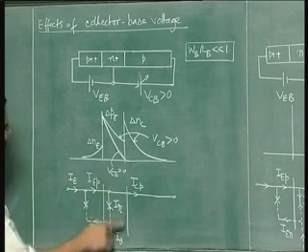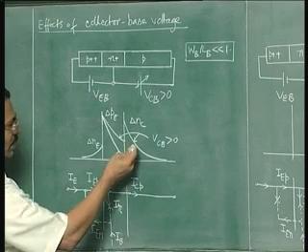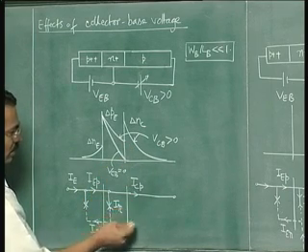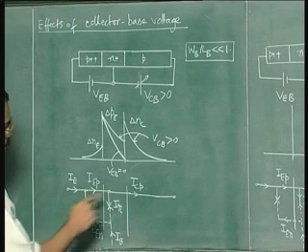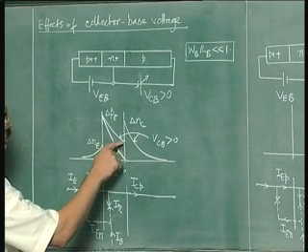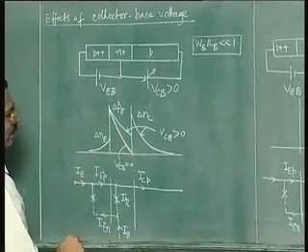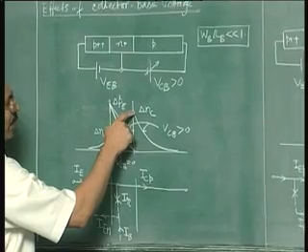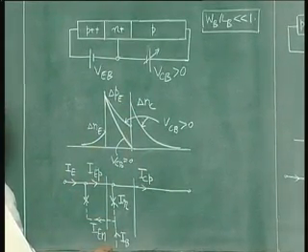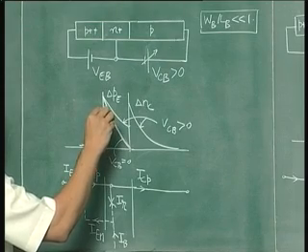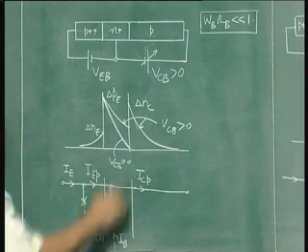Now for VCB equal to 0, this was the flow diagram. There were no electrons in the collector, there was no electron current. But now you can see from here that ICP exists because you do have a slope of holes at this junction, even for collector base forward bias. But in addition you also have ICN because the electron concentration also is raised. Now the current because of electrons is related to the initial slope of this carrier distribution.